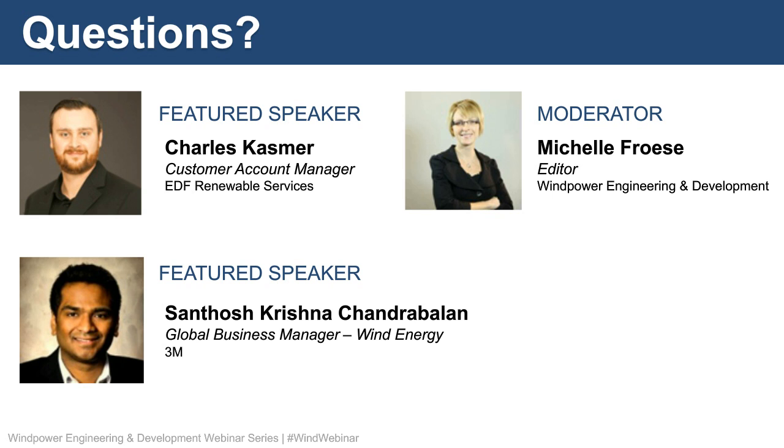And back to the VG specifically, how many vortex generators can fall off before turbine production is affected? It can also depend a little bit on the blade and turbine. So generally up to 10% of them is okay. It's designed into the factors. In some cases, we can even have more leeway. So it slightly depends upon the turbine and also the blade.